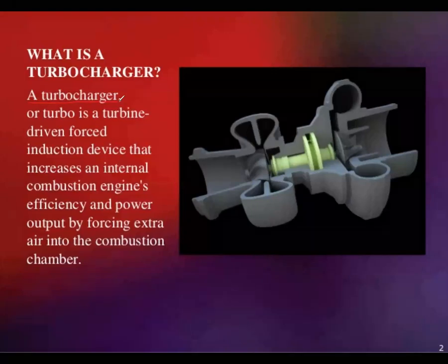Turbo means turbine. By using a turbine, the charging takes place here. So a turbocharger, or turbo, is a turbine-driven forced induction device that increases an internal combustion engine's efficiency and power output by forcing extra air into the combustion chamber.